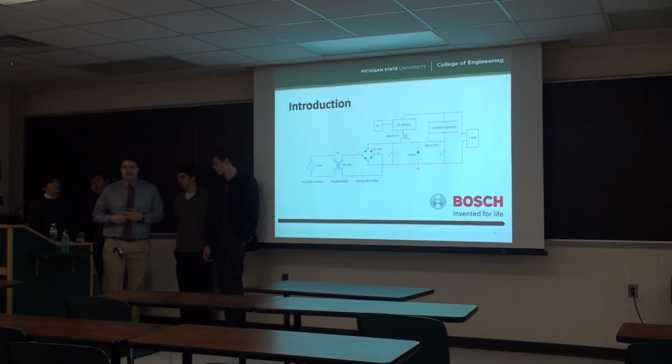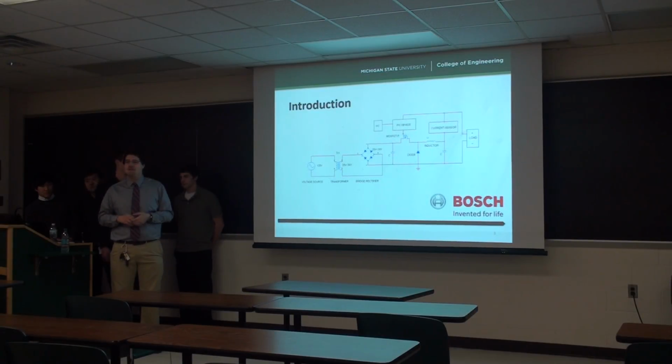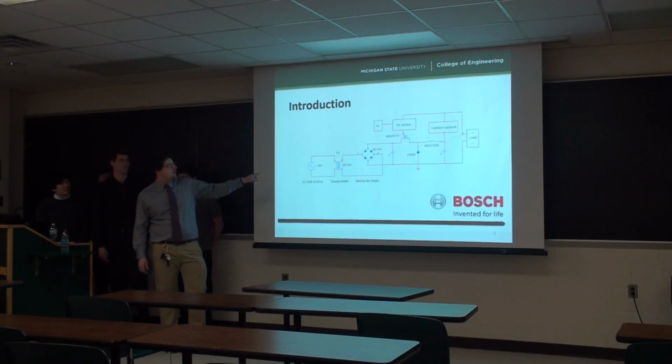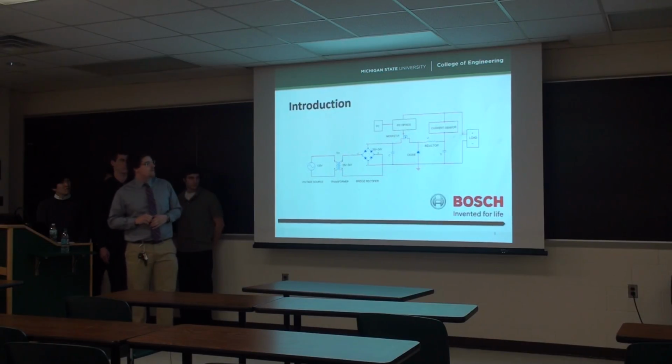So our project is to make what Bosch called an automated power mode test system. Now what that means is it's essentially just a power supply which you can program to emulate certain voltage waveforms. And how we propose going about this roughly is, showing you preliminary, we have our transformer and rectifier like you find in a typical power supply. And after the rectifier you see what's called a buck regulator, and that's what the circuit will be using to regulate the voltage, and Chris will talk more about that for you.